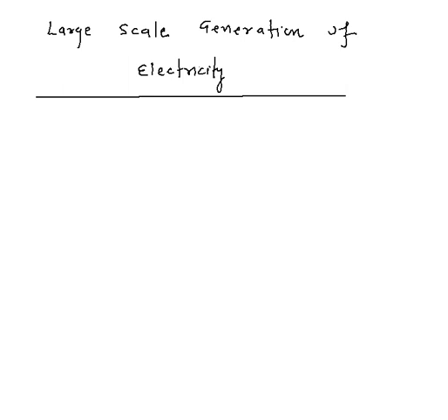So with the soft iron core, the combination with the coil is called armature. Armature is coupled with turbine. Turbine has blades. You hit the blades by some mechanism, make the turbine turn, and as turbine turns, the armature turns, and as armature turns, the coil is turning, and as coil turns in magnetic field, you have induced EMF.